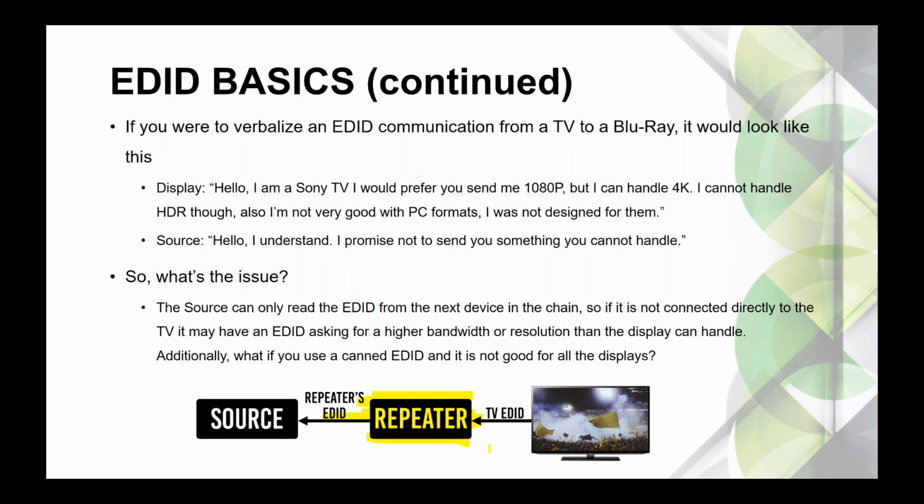When these do not communicate directly, when a repeater gets involved, then we need EDID management to either force an EDID into some settings that the display can reproduce, or it needs to be built into the repeater product, or we need some kind of a device to fix that. And I'm sure a lot of you have run into this and know what I'm talking about. We're going to talk about how to fix it in the next couple of slides.